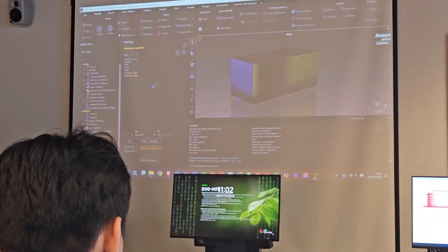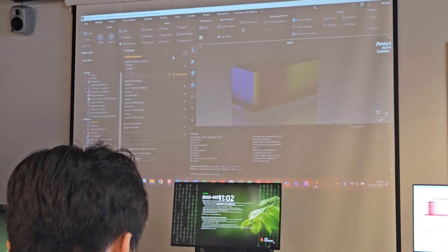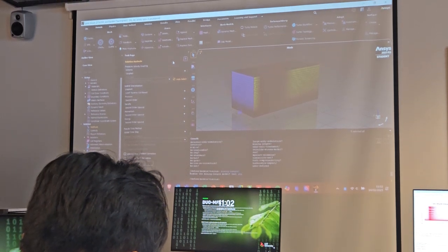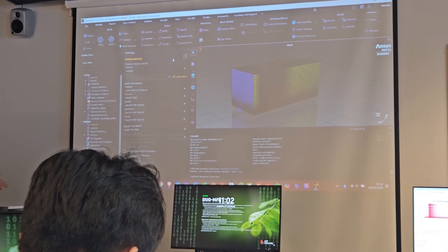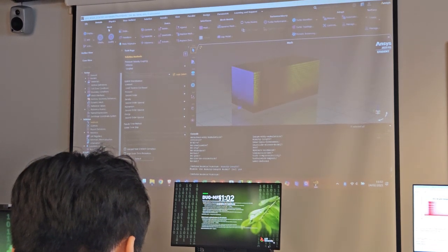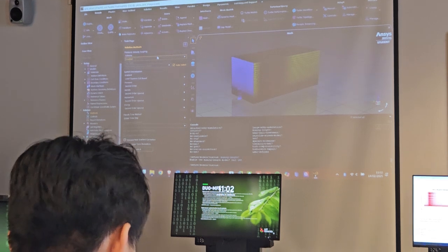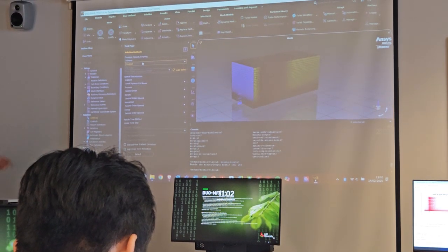So in methods, here we can choose some numerical scheme. It's not a purpose of this course, let's say, to explain what these are. So we are just going, most of the time, with the default options. I use this coupled option. This is coupling the pressure and velocity.